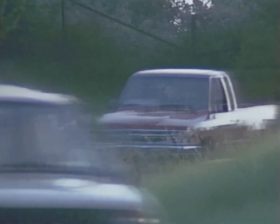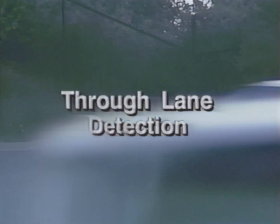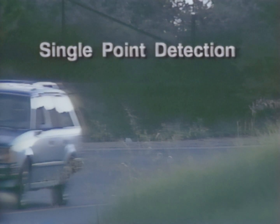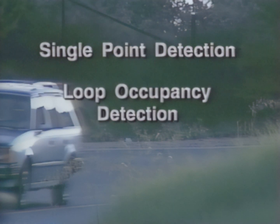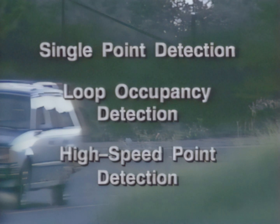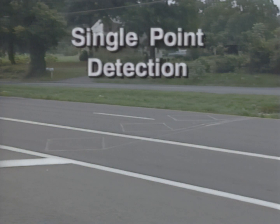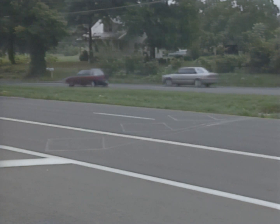The detection of vehicles in through lanes depends on the approach speed and the controller operation type. Detector designs for through lane detection include single point detection, loop occupancy detection, and high speed point detection. Single-point detection is the simplest form of through-lane detection used for actuated controllers.